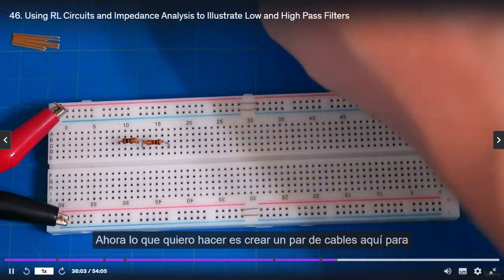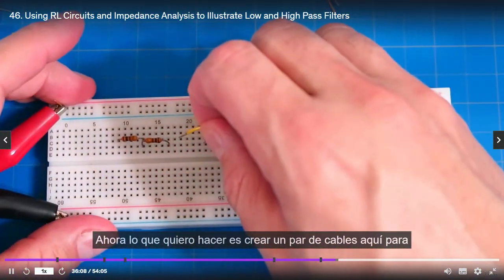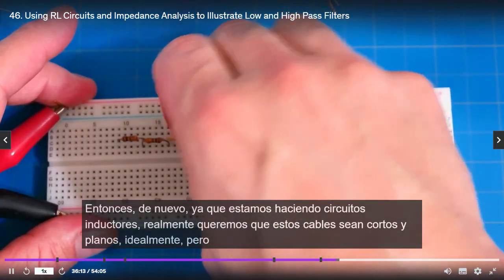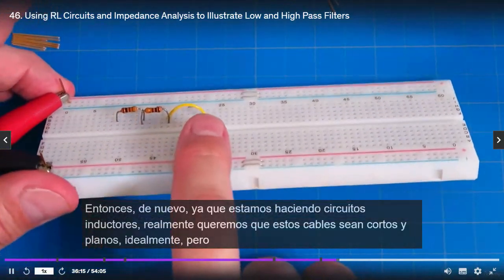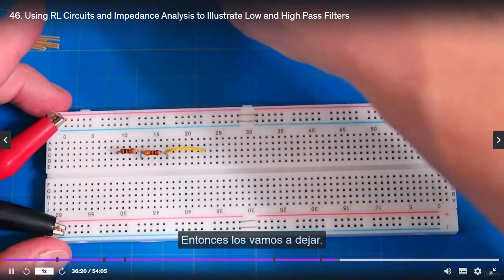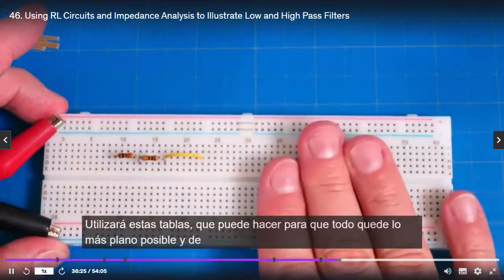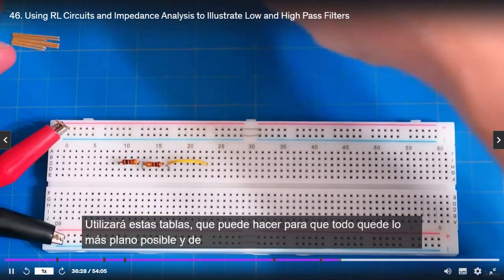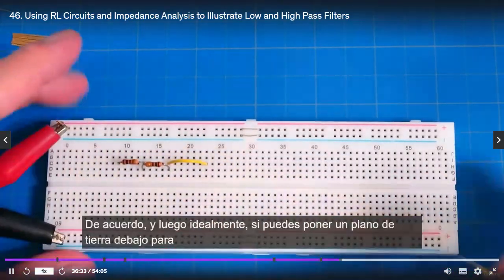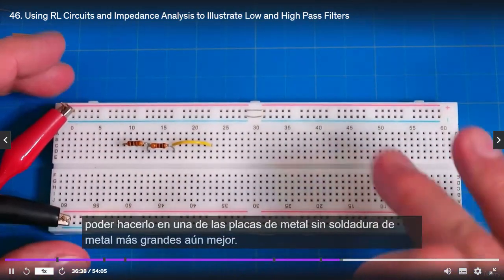Now I'm going to create a couple lengths of wire here so that I have some space for some instrumentation. Since we're doing inductor circuits, we really want these wires to be short and flat ideally, but I don't have time to make everything flat and pretty, so we're just going to leave them. But when you do this, I'd like you to make everything as flat as possible. If you're going to use these boards, which you can do, just make everything flat as possible, and that way it'll work better. Ideally, if you can put a ground plane under there, so you can do it on one of the bigger metal solderless breadboards, even better.